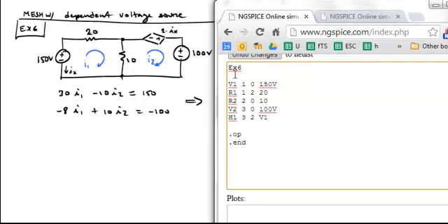All right, so that says the controlling signal for this current controlled voltage source is the current that flows through V1. And the sign convention, it uses the passive sign convention. So when I say V1, it means current flowing into its positive node, i.e. flowing from node 1 down through the source into node 0, which is precisely the orientation that we have depicted Ix as. The last piece of information we need now is what is the scaling factor, and that is 2.